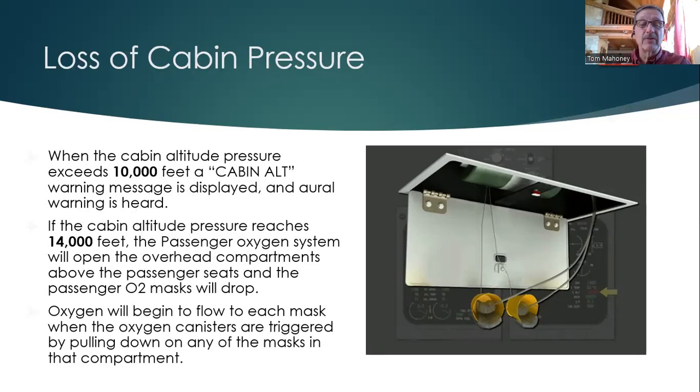For example, if we forgot to pressurize the aircraft at all before we took off and we fly up to a pressure altitude of 10,000 feet, that would be the same as having an unpressurized aircraft, and we would get these alerts. If we were at, say, 30,000 feet and we began to lose the cabin pressurization, by the time the cabin pressurization reached 10,000 feet, we would get another cabin altitude alert, and again, an aural warning. So in the case of depressurizing the aircraft intentionally for an emergency depressurization, we're going to bring the cabin altitude up to 14,500.